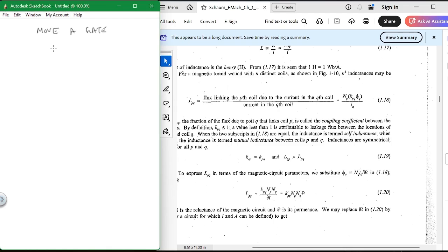That's about it. Well, not really, because you have to think about it for a little bit. When this thing turns on, what does the current do? If you look at time and you look at current, it does something like this, and it comes back like this. Why does it do this bump at the beginning? Well, when there's a big gap between where it's going and where it ends up, there is a high current required to energize that relay. In other words, to energize that circuit, it takes a lot more current. When there's a large gap, a lot of energy is required. When there is a small gap, less energy is required.